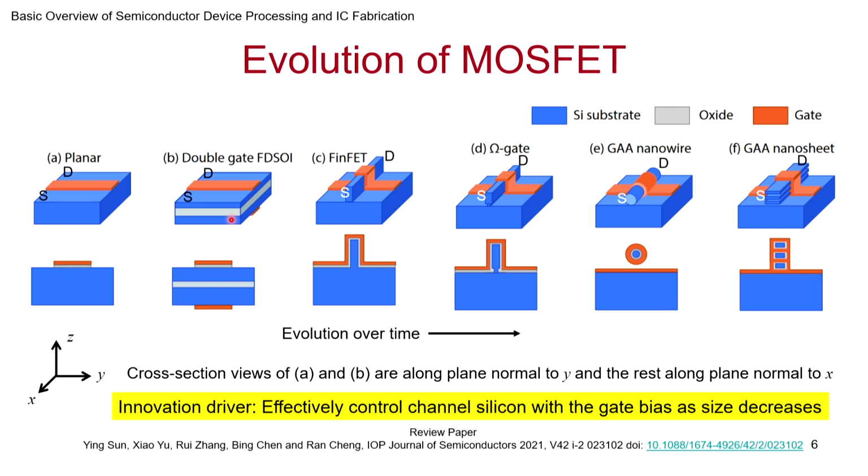Here, on the other hand, you have the gate and the gate oxide, gate poly, the thin silicon, and then you have an SOI, right? Silicon on insulator. This is the silicon that is sitting on the insulator, that is a buried oxide. And the bottom is again silicon, and you can control that electrostatically by putting a contact at the back. Of course, these dimensions are not to scale.